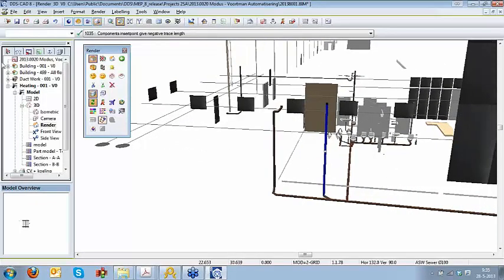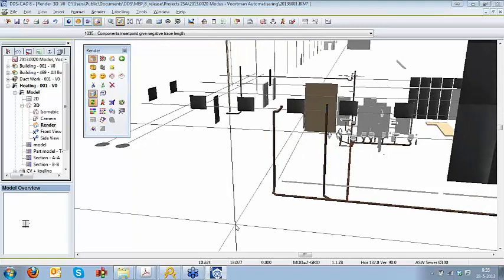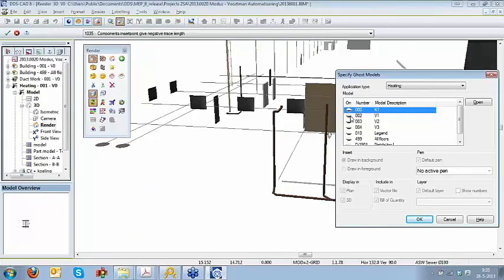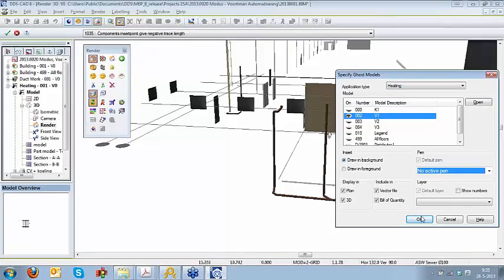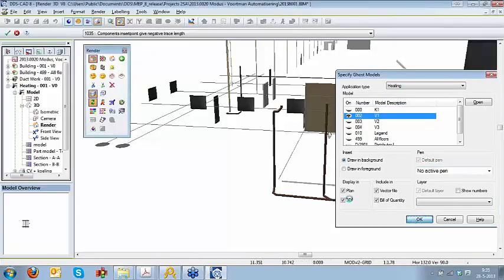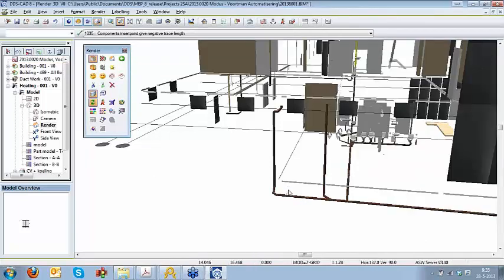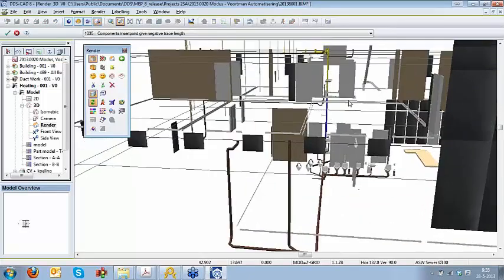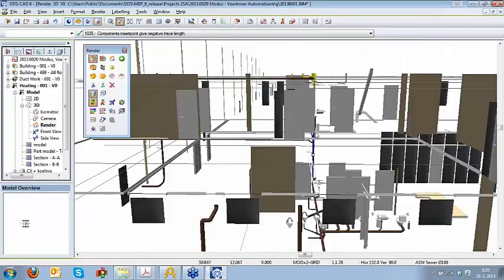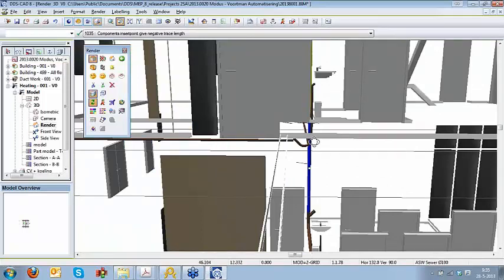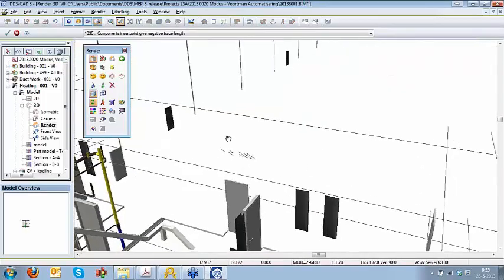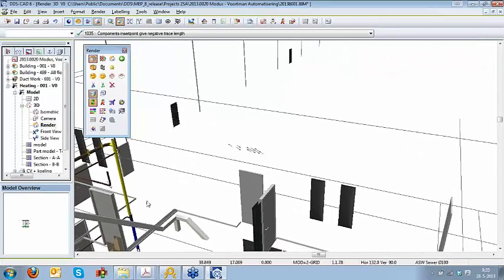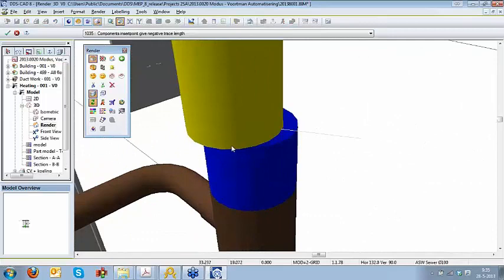So when going to the project menu and we activate the second floor in our heating system, we can see and also use the same coloring to represent also the connections on the next floor. So in here, what we can see in the center is a connection which will show me the information and connections to the floor above. So this is also now part of the system with the connections available.